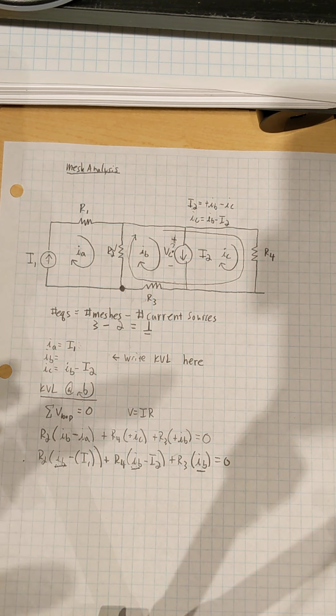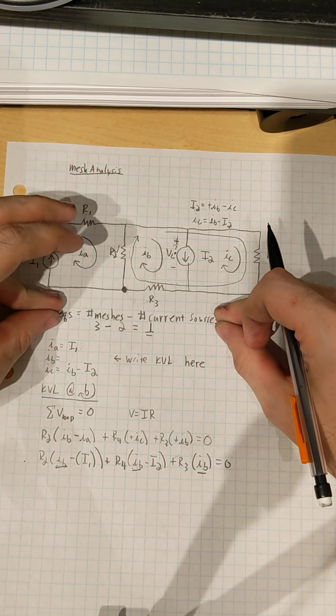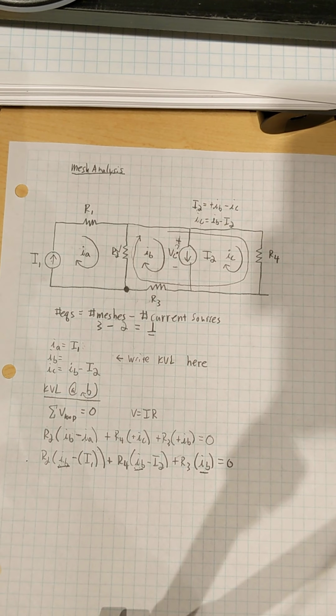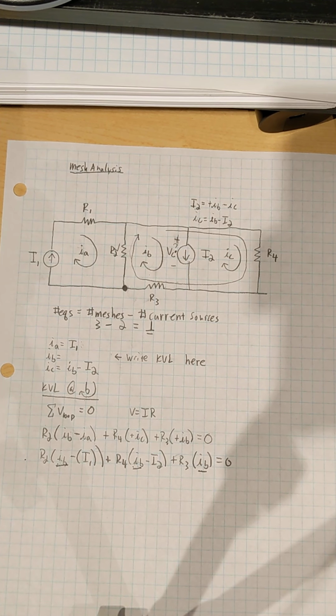When you have a combined problem, what you'll do is look at both methods first. You won't set anything up. Again, you'll just look at the number of equations that you'll need to solve and pick the analysis method that requires the least amount of equations.